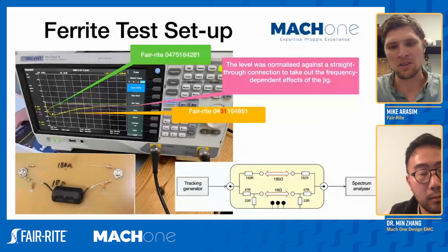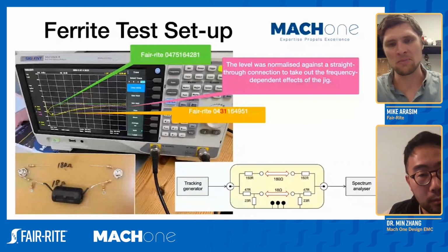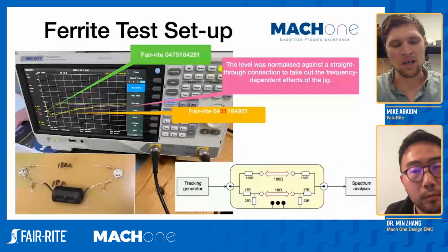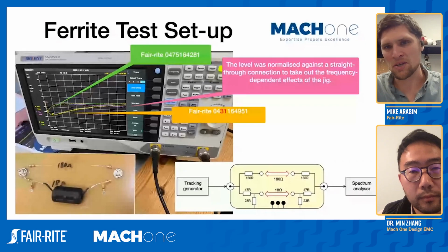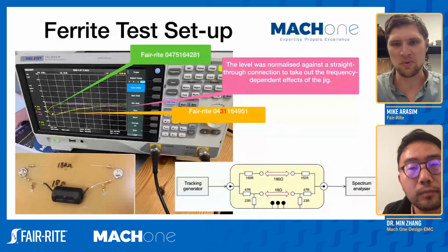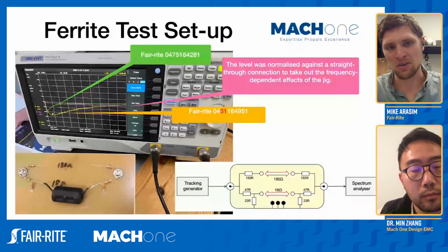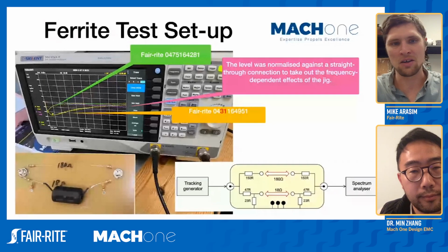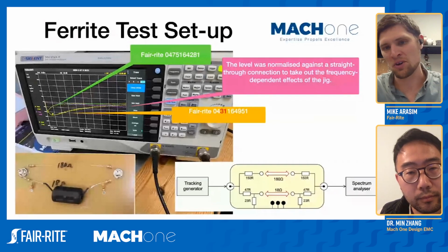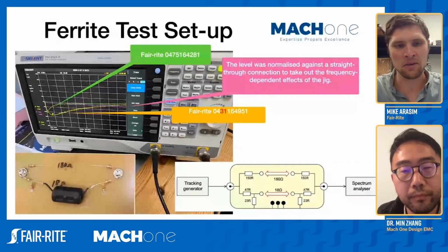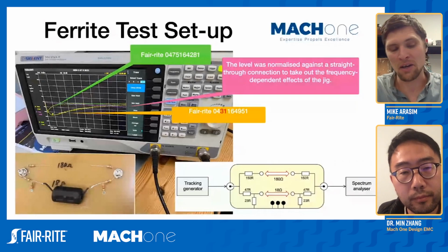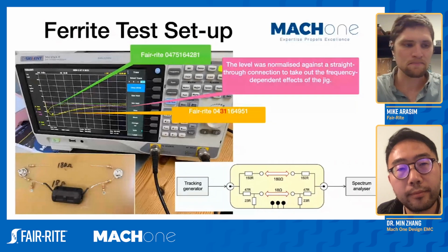We have some of the test methodology outlined on our website. It's fairly basic loop-to-loop coils with the sheet in between or perpendicular, depending on the test method. We look at reflected and admitted coefficients, S parameters, to calculate that. But that's pretty much what we do internally.